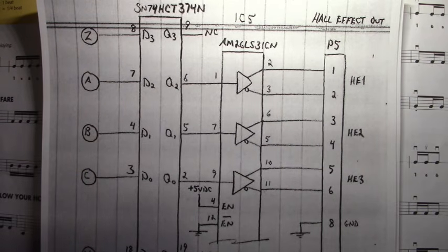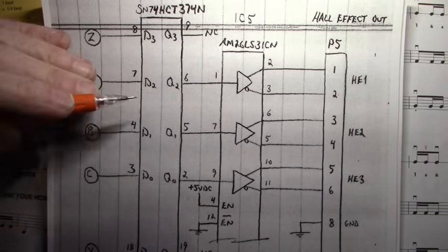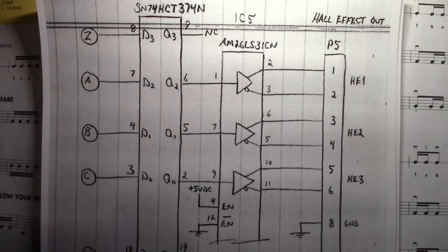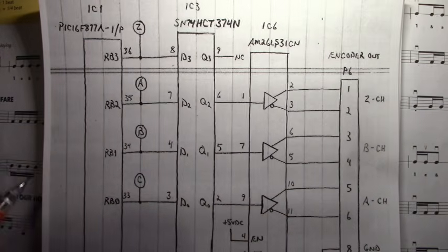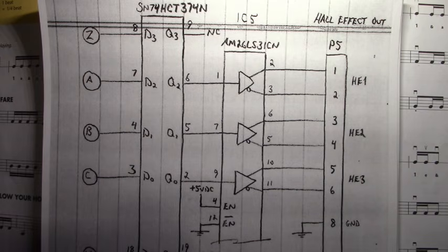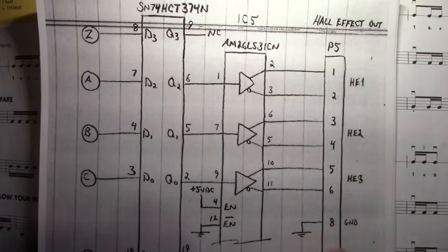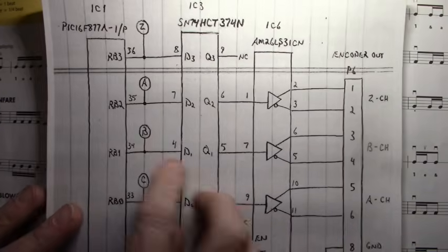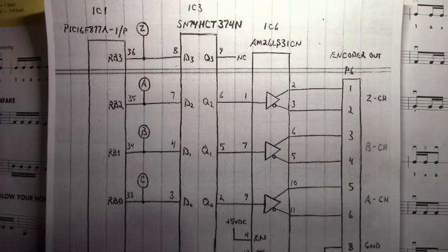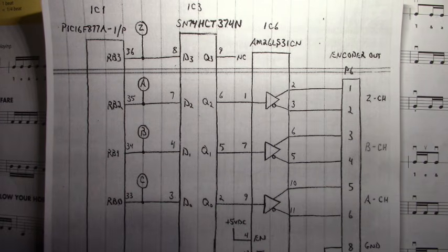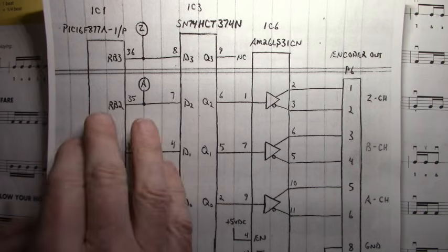So I have to select from the code, from the microcontroller, where that data from these inputs go, either to the incremental connector or the Hall effect connector. So here is our incremental side, and here's our Hall effect side. And that is for the differential output. So we can clock the data either here to this connector, this is another Phoenix connector, or we can clock the data to this connector. So depending on how the Hall effect encoder simulator is programmed, determines where the pattern goes.